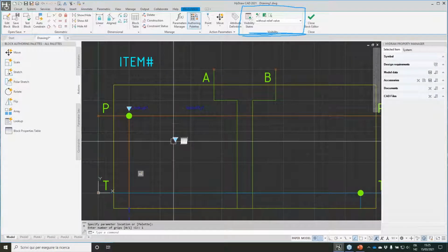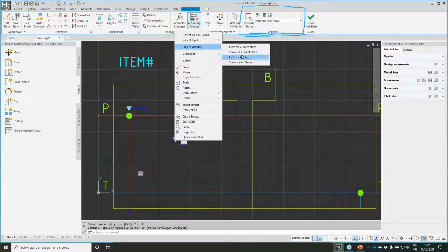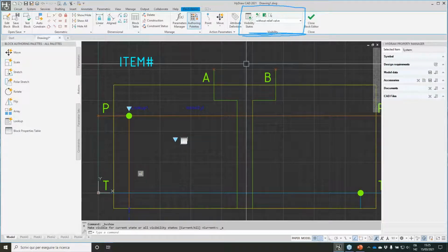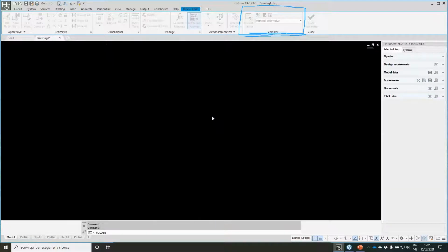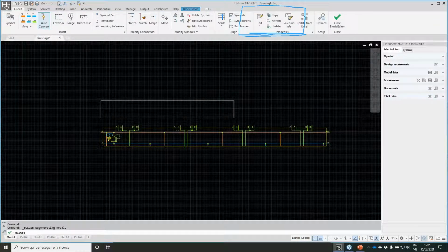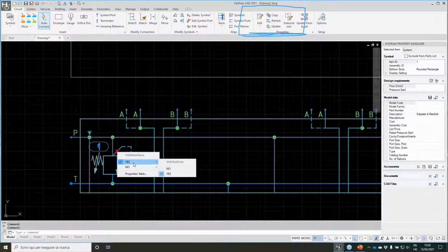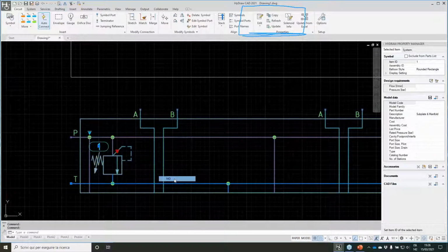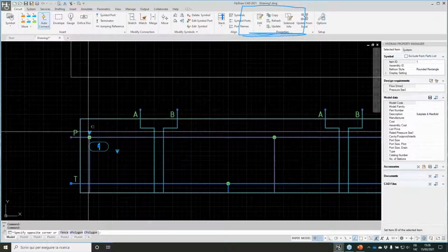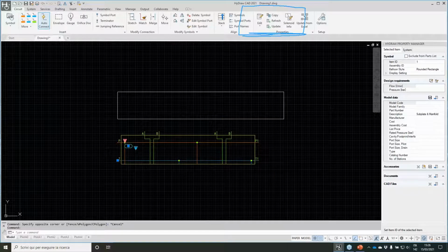As you see, let me right click visibility and apply for all states, so I want this toggle to be visible for all states. Now let's see how this is working. So now this is my control. With relief valve, yes or no? Yes, I want the relief valve without test point. Or no, I want nothing. And I am always able to switch to 2 station or 1 station or whatever.